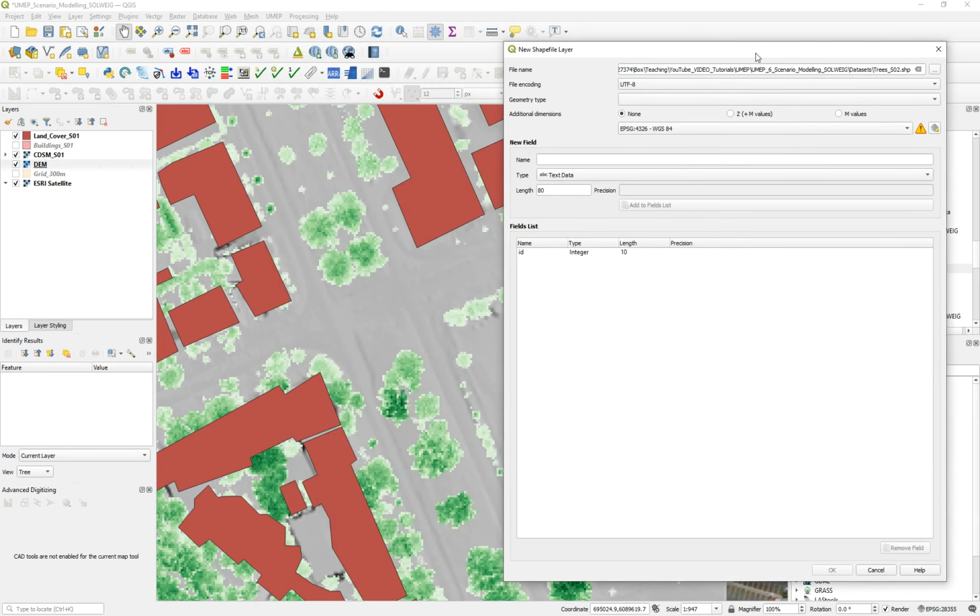If you don't want these trees to be there, or we are going to remove trees, what you have to do is go to your original LiDAR datasets, remove the trees from the LiDAR, and then follow the steps that I explained already in my previous emails on how to generate your own spatial data.